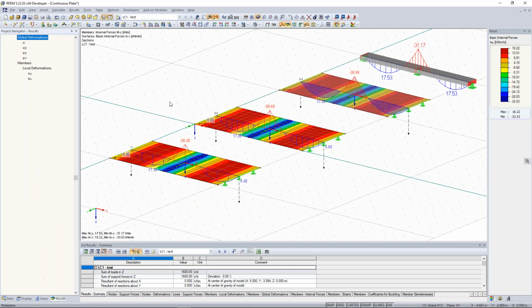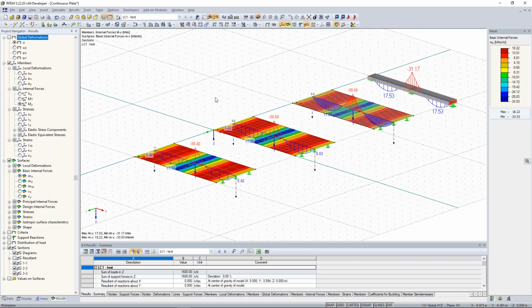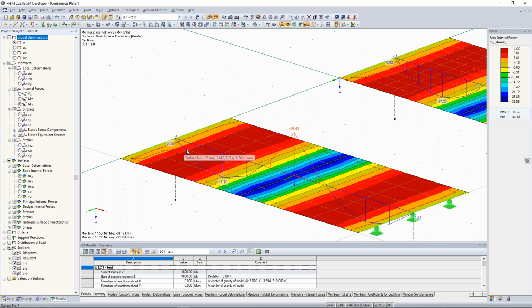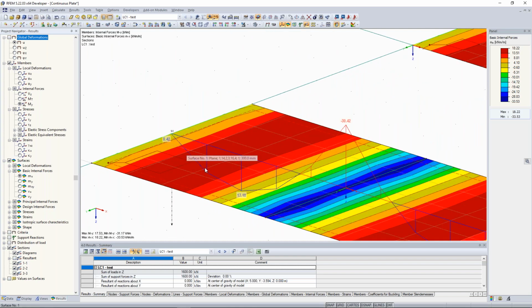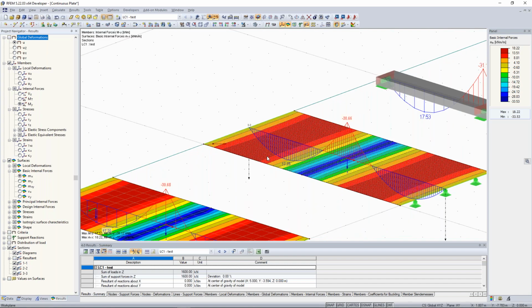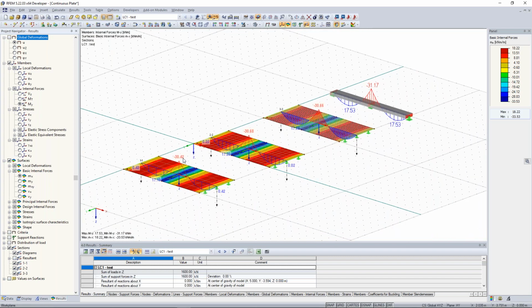the sections. Now I see the different results. Good. Now you can maybe see also the different results of the sections, yeah, and also the different sizes of the FE mesh, because here we have 1.1 meter, so at every 1 meter there is a result, and here 0.5 meter and here 0.1 meter. And what I want to show you is that it depends which FE sizes you have, because it can cause different results. Good.